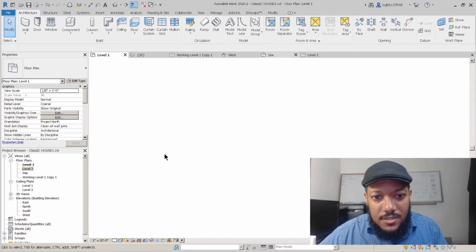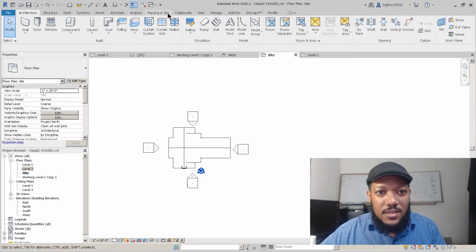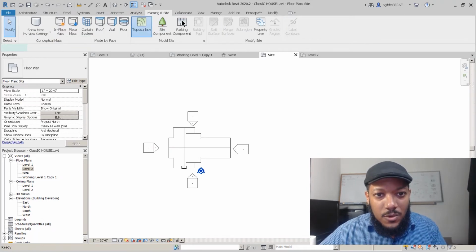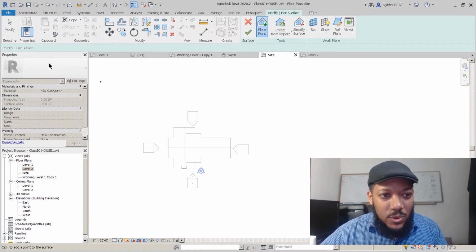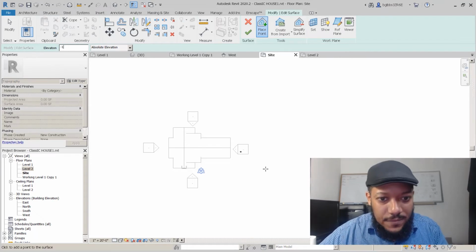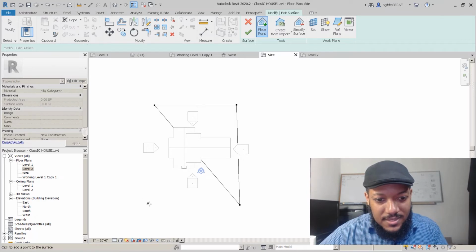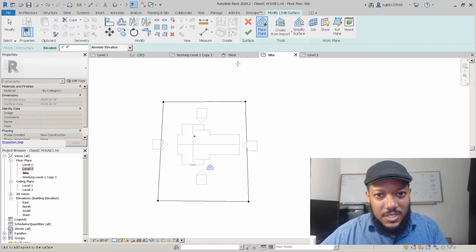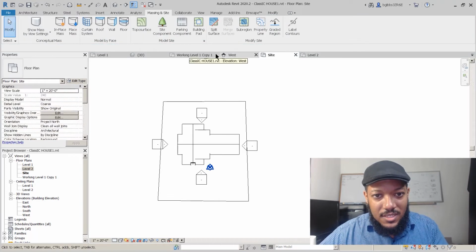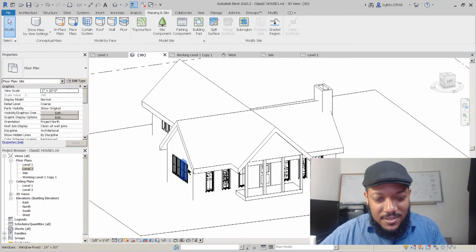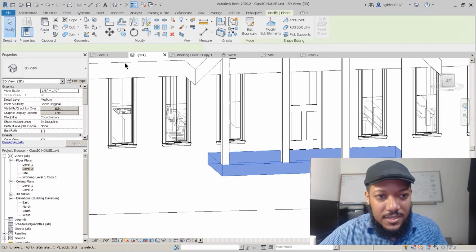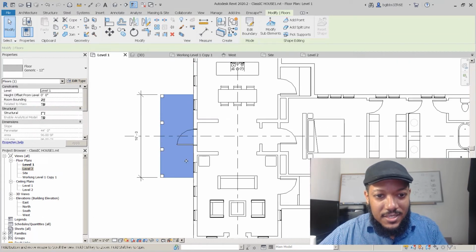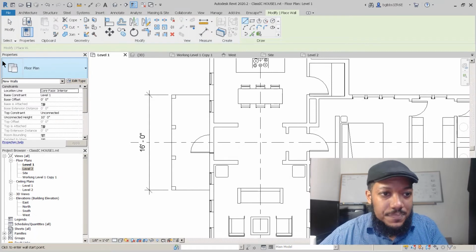Right, from our site drawing, the way to create a site is going to our massing, and right now we're going to make a semi topo. We're just going to have points at -1 feet. And we're just going to make 4 of them just out in space. And our building will be pretty basic. So but you'll see in our model now that we have a ground, and our porch is a little bit floating. So what we can do is make some walls, and now we're going to make some custom walls.